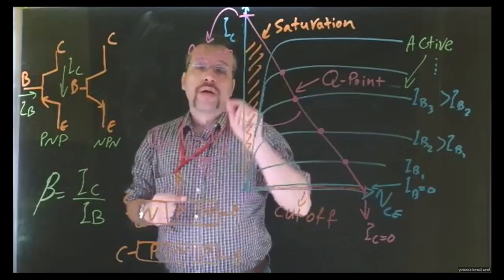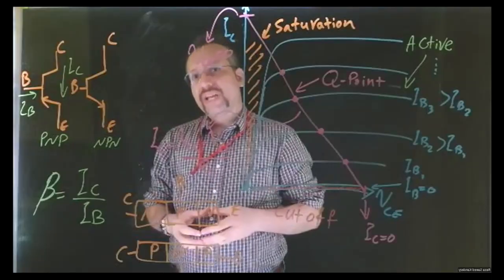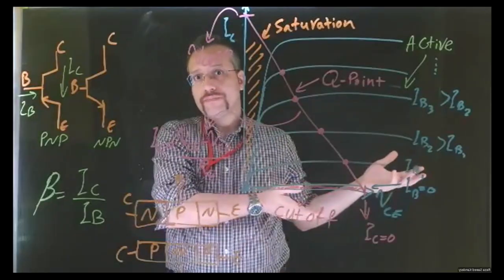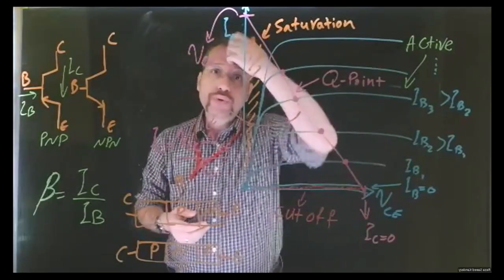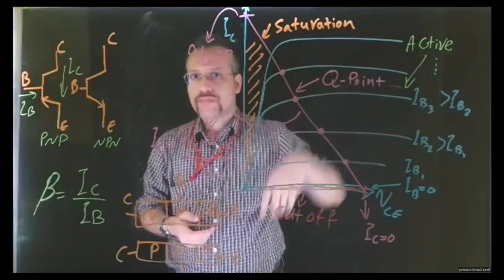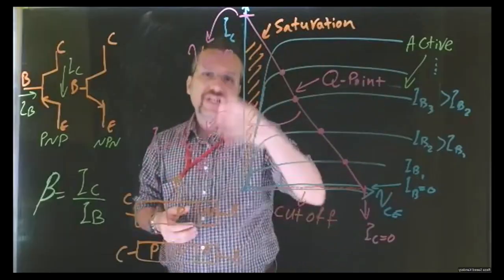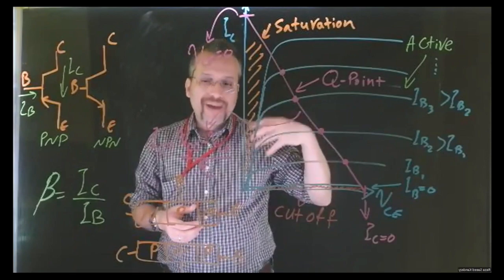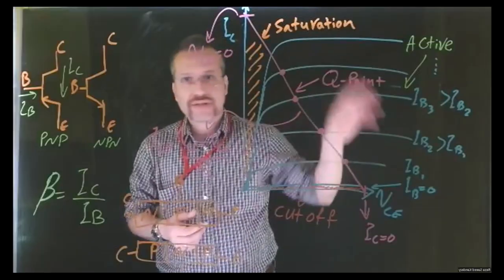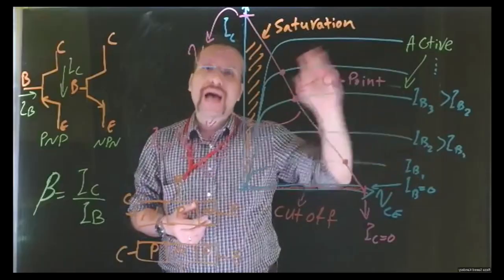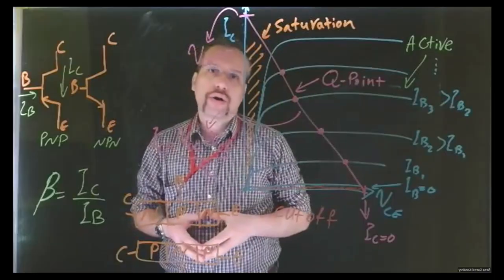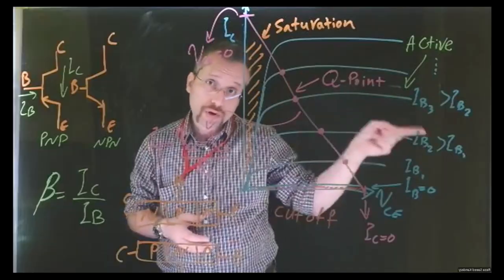Another main difference is that when we work with a FET, whether MOSFET or JFET, the current passing through it is basically mandated by the circuit. Whatever voltage and resistance are in the circuit decide how much current passes through the FET.